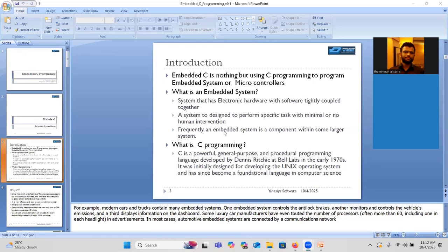No, sir, it's application specific. Yes, I can use the word that the instrument cluster module is a microcomputer. Generically, I can say that because it can do the computations. It is adding the odo values and displaying the trip computer, and it receives information from different sensors. If there is a fault, it makes the decision to display the warning. If there is a change in the speed, it makes the deflections in the speedo gauge.